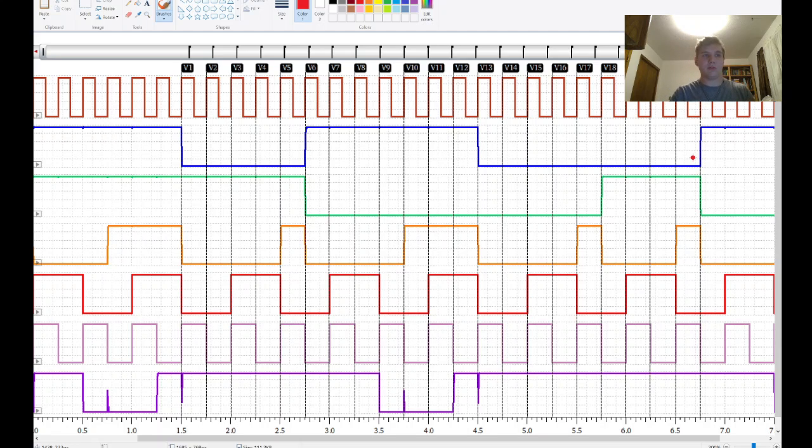And so we see that from these 22 different high rising clock edges within this waveform, we start at state 2. The reason why we start at state 2 is because what we've seen before with sequential logic circuits is when you demo them or simulate them, they start at a random state. We saw that this started technically with 2 invalid states until it found its way into a valid state. Once we were at that valid state 2, it continued on the state transition diagram in accordance with how it's supposed to be implemented.